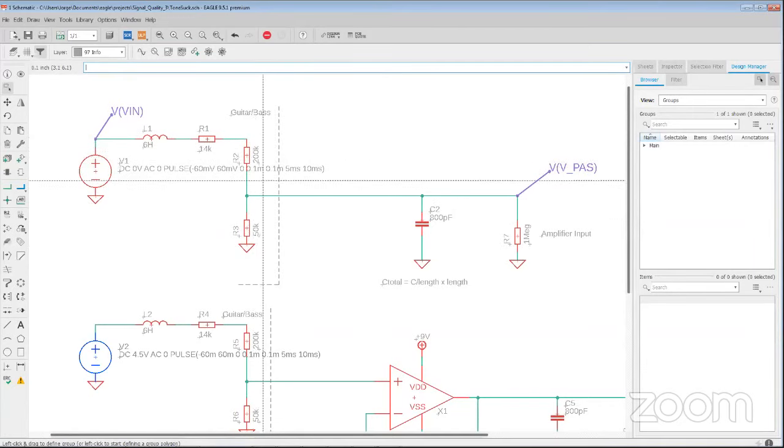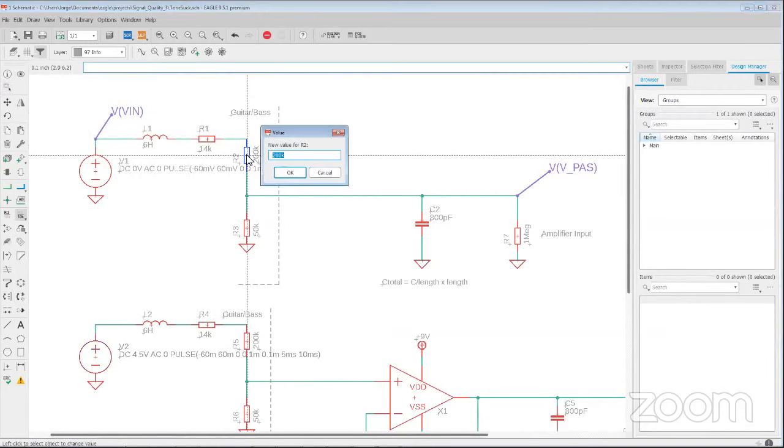Okay, in that situation, things may change a little. So let's go ahead and explore that. I'm going to go to values. I'm going to put this as 1 ohm because you don't want to have a dead short. I'll make this 250K. Make this one 250K. And I'll make this 1 again. Okay. So now let's go ahead and simulate it and let's see what happens.